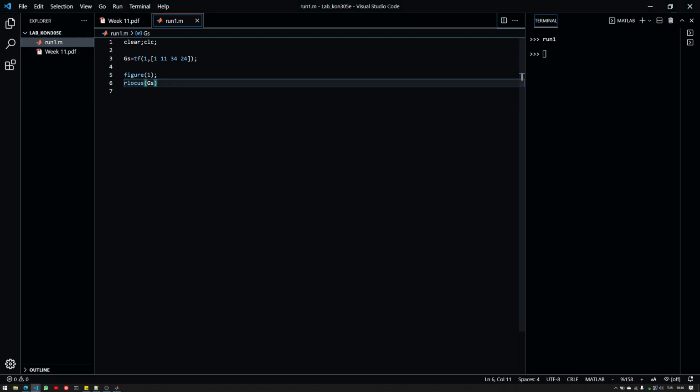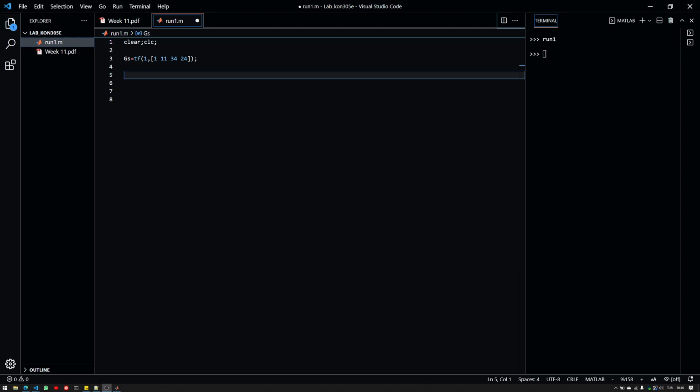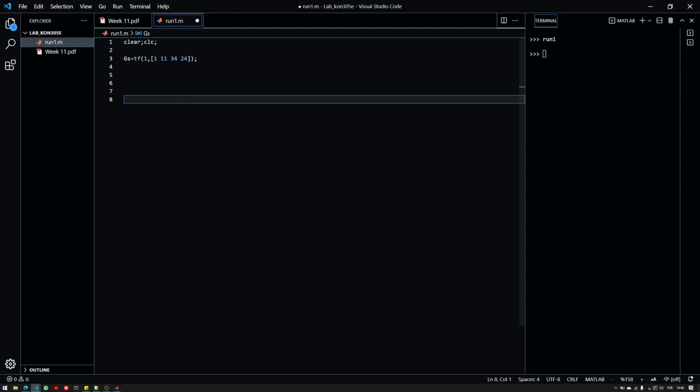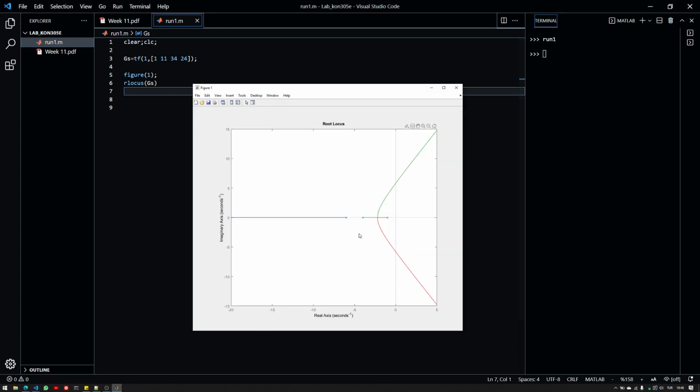As I've mentioned before, we need the poles and the zeros. Now the angle condition is stated as follows. Let me just leave the root locus plot, by the way. We need to place a destination point here, and each pole will be used to draw a line to the destination.